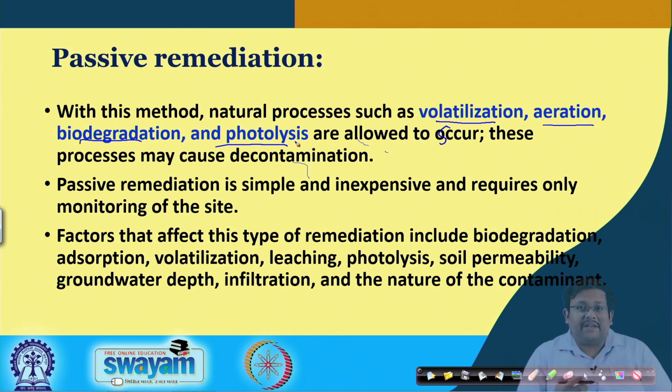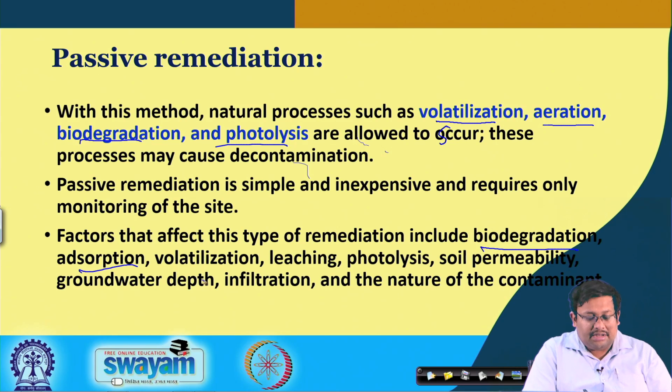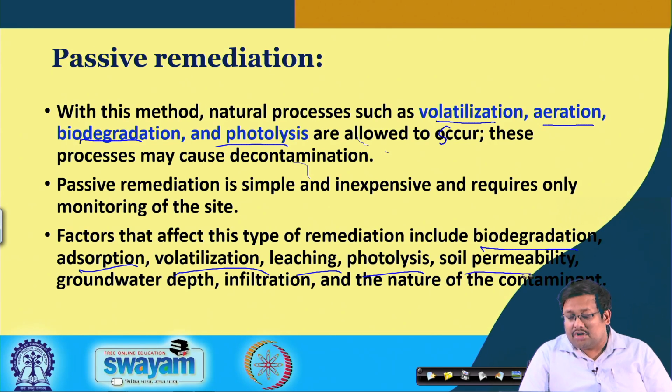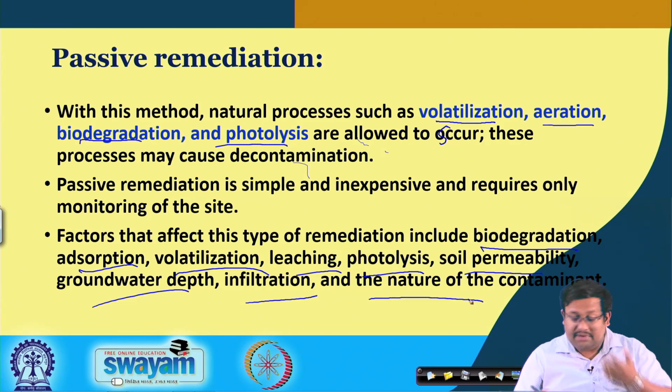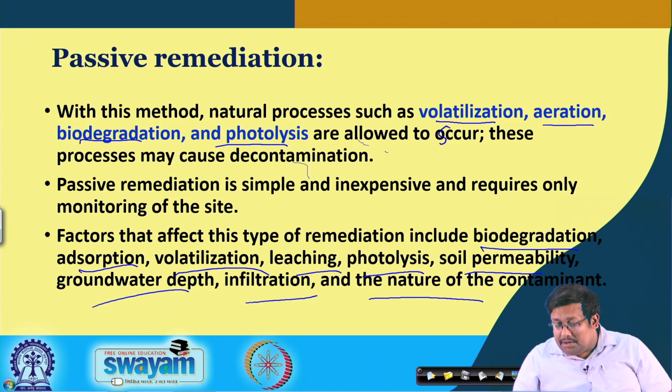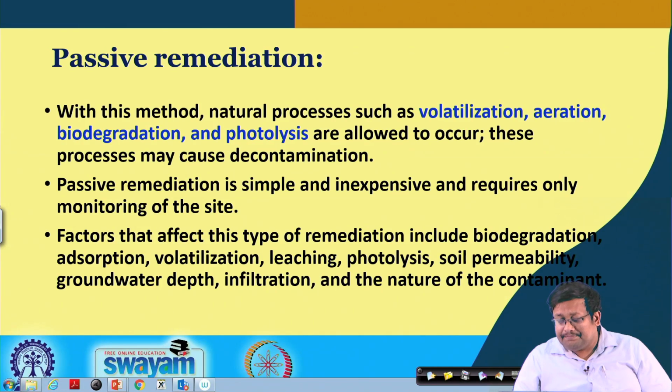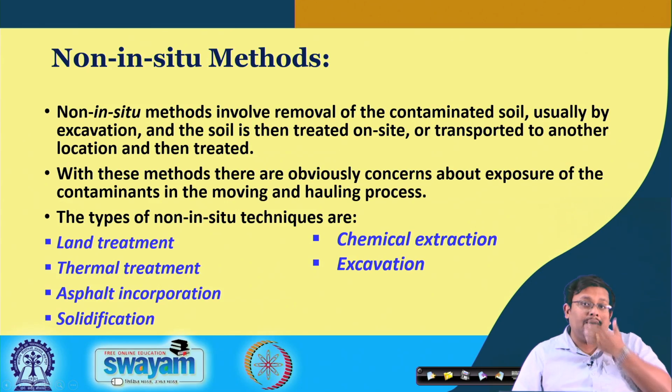There are several factors which affect the remediation, including bioremediation, adsorption, volatilization, leaching, photolysis, soil permeability, groundwater depth, infiltration and nature of contaminants. All these factors are very important, as they impact passive remediation. So, let us move ahead and see what the different types of non in situ methods are. Sometimes we call them ex situ methods also.